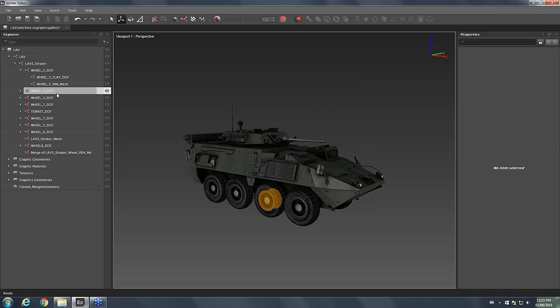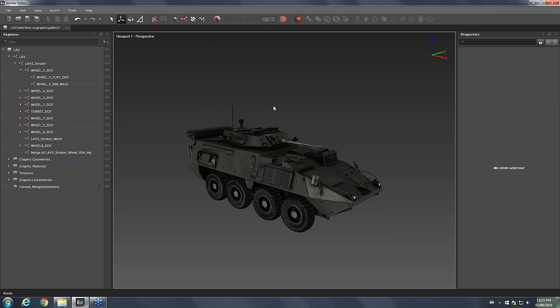So you can go on like this, and when you receive the model, create a hierarchy that will make sense. You can rename the node, you can reparent the node in order to create a model that's going to be easier to transform into parts, and finally, which is going to be simpler and lighter to use in your simulation.